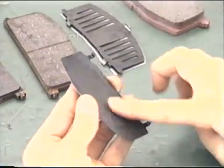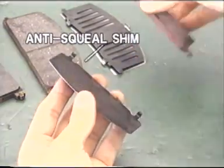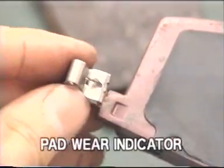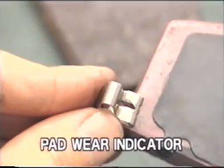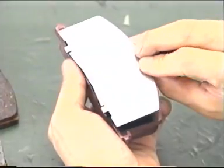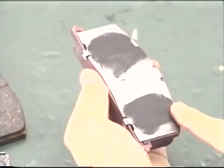Apply grease to the anti-squeal shim and assemble to a new pad. Install the pad wear indicator plate to the inside of the new pad. Be sure that the arrow on the pad wear indicator plate is pointing in the direction of rotation of the rotor disc. After installing the anti-squeal shim, apply grease on the contact point of the cylinder.